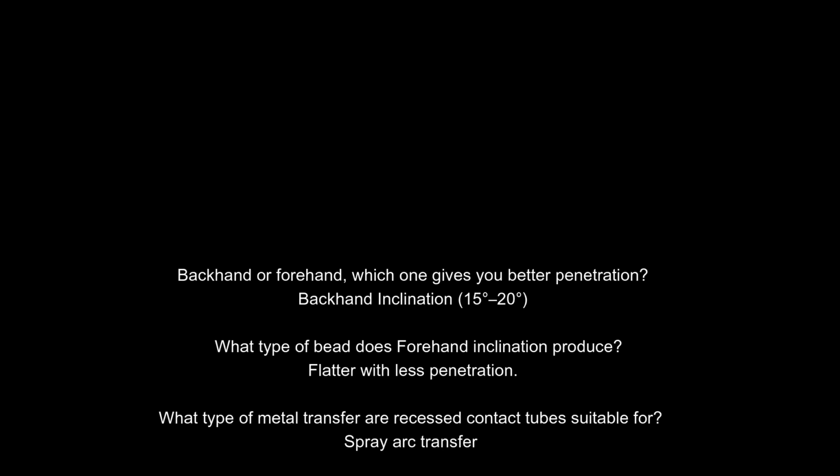Backhand or forehand, which one gives you better penetration? Backhand inclination, 15 to 20 degrees. What type of bead does forehand inclination produce? Flatter with less penetration. What type of metal transfer are recessed contact tubes suitable for?